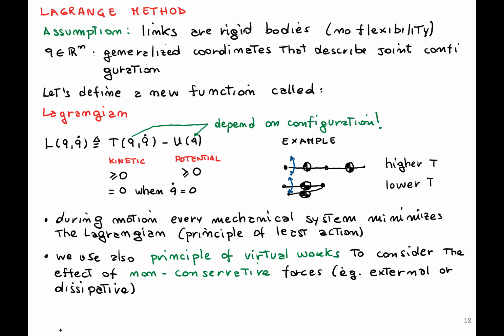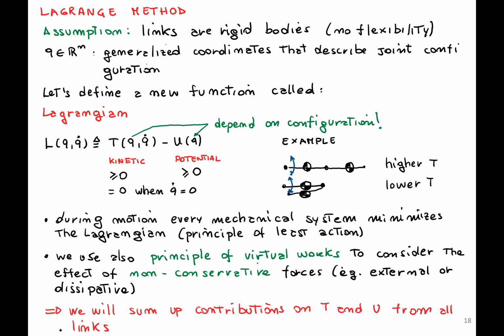In case we have, for example, Cartesian forces, we need to compute the Jacobian of the point of application of that Cartesian force, and using the Jacobian transpose, we compute the corresponding torques, because in the case of a robot with only rotational joints, the torques are the forces related to the generalized coordinates. Okay.